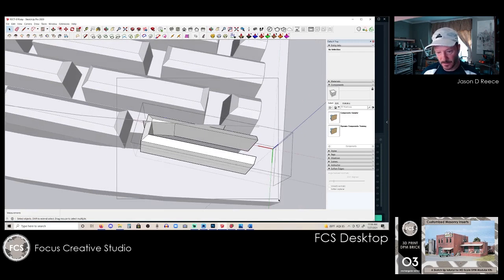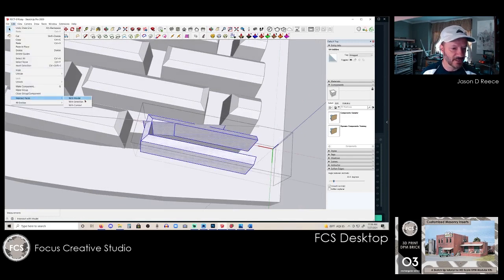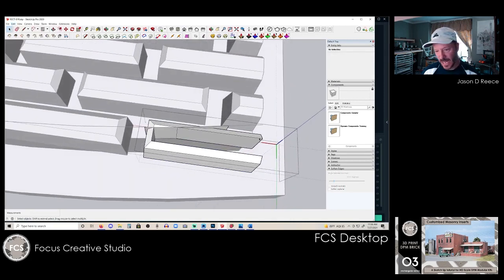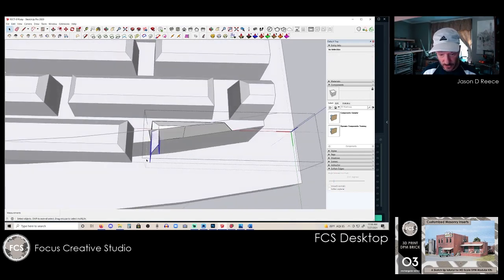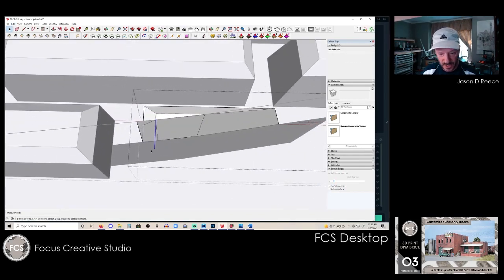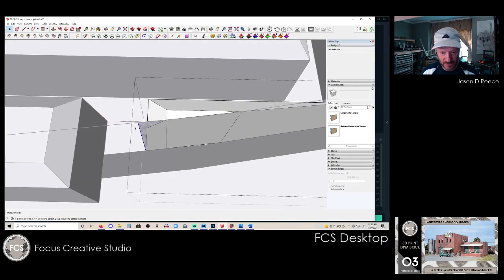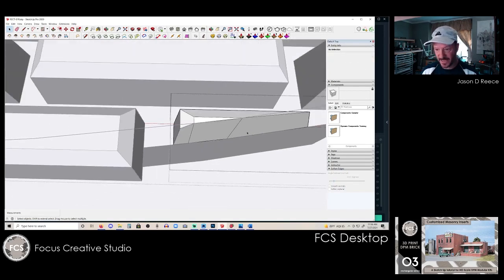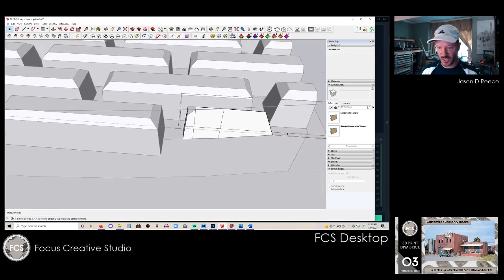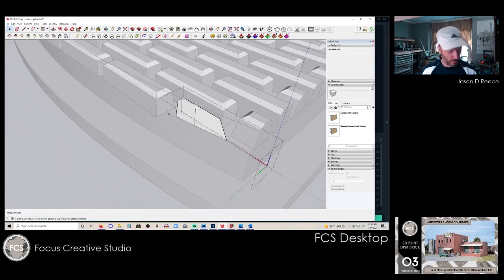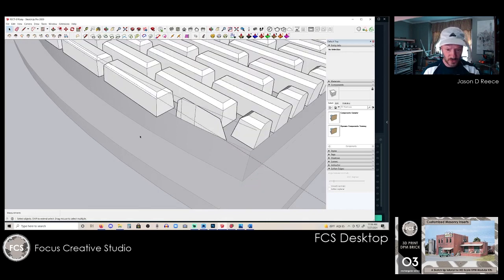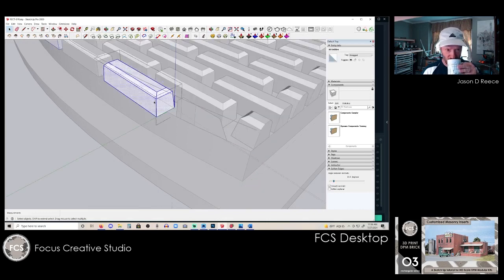I'm going to rectangle window everything, come down, Edit, Intersect Faces with Selection. Now everything that I just modeled here, I don't need. But those planes slice through it that allow me to cut that, and now I've got those planes that have created the finishing faces for that particular model. So nice clean geometry, even though it's a little odd, but now it's clean and will print just fine. So double click, get out of that one, go into this one.